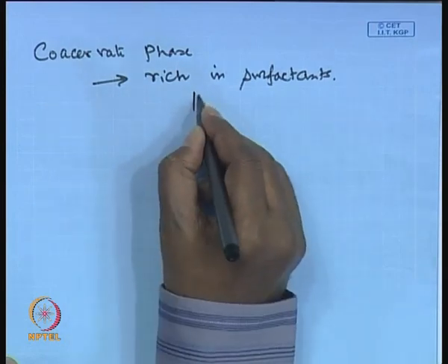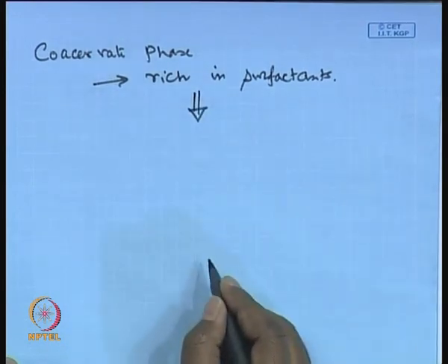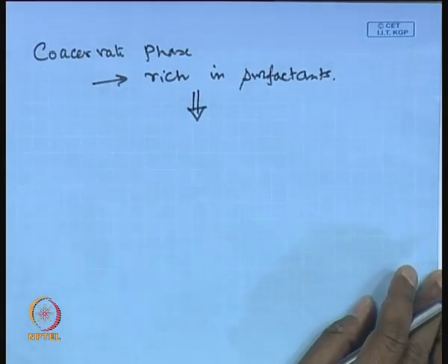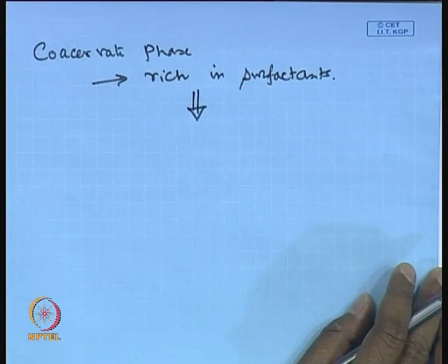Okay. Because most of the non-ionic surfactants, when we talk about micelle enhanced ultrafiltration, we will talk about the critical micellar concentration. Mostly these non-ionic surfactants have a very low critical micellar concentration. So, if you have a concentration slightly above that, you will be forming micelles. Now, if you increase the temperature of the surfactant solutions, these micelles will separate and go into the coacervate phase.